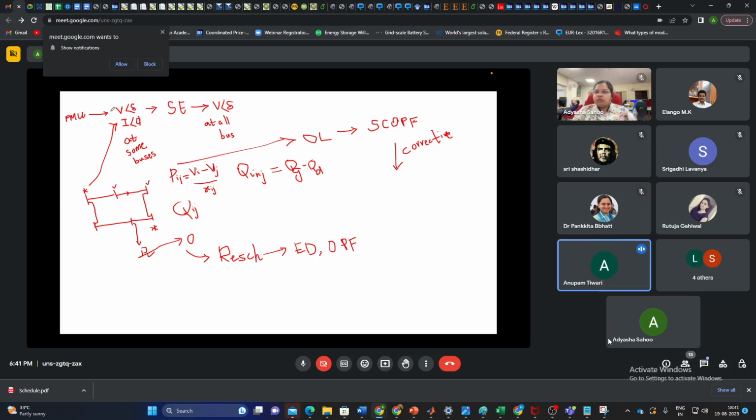That is how peak load is served. Similarly, nuclear power plants always run in the base load only. They are also not reducing their power. So basically, we have to classify power plants as peak load power plants or base load power plants. Normally, small hydro plants or the hydro plants take care of the peak load, and coal and nuclear power plants take care of the base load.